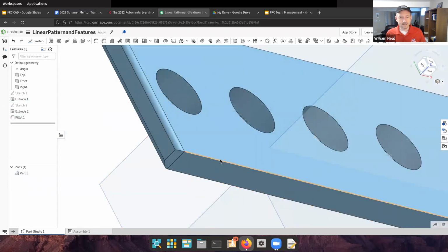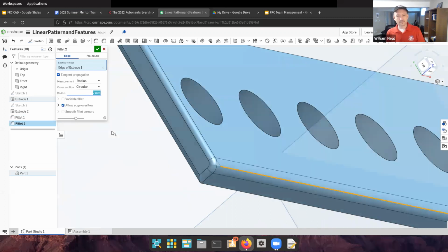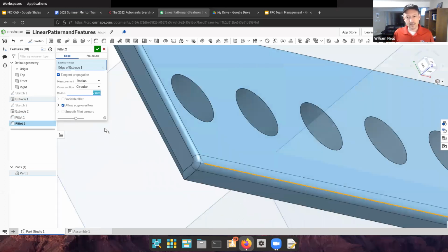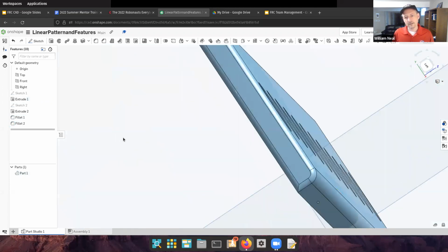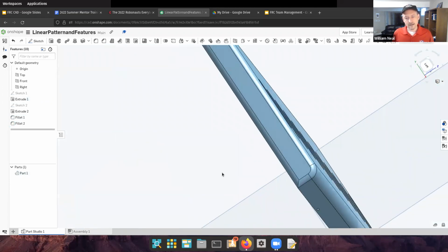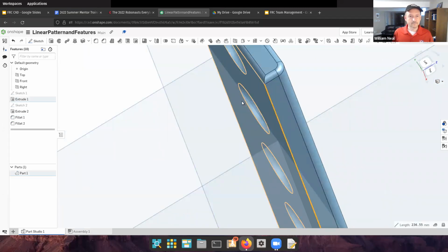And let's see if that allows me to do that on a single edge. So I just clicked this edge and I'm going to try a single fillet. Let's try this one 2 millimeters if it will let me. Yeah, it does. So I took off 2 millimeters on that edge, and then you see my next fillet. There's a 2 millimeter edge there. Let's try on this other edge here. Click it with my left button.